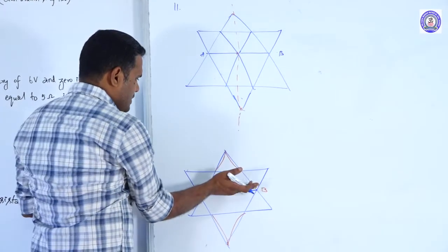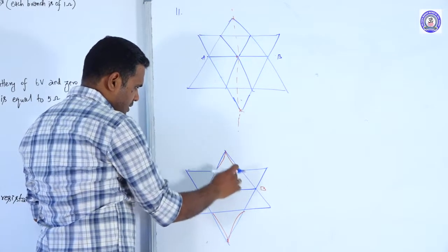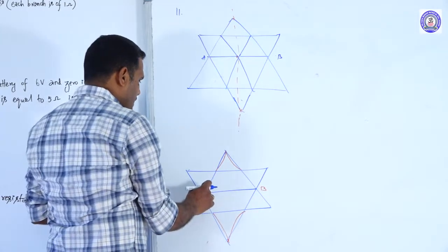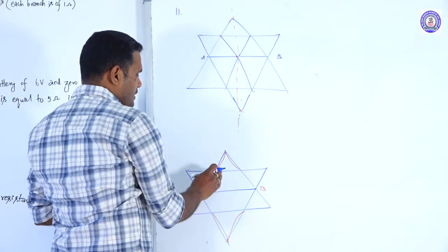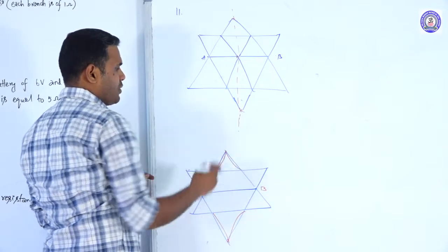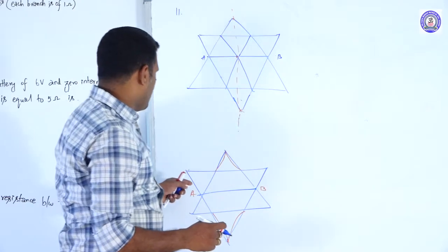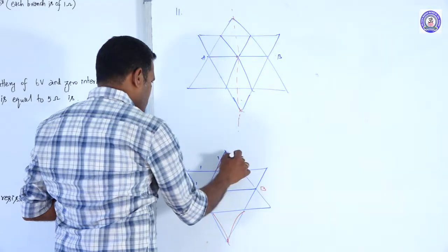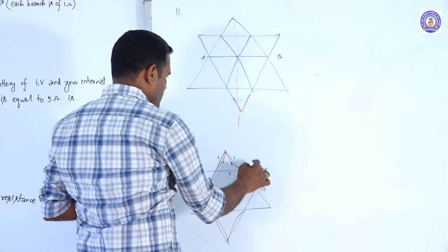Now, there is a symmetry about this reference line AB. This circuit arrangement and this circuit arrangement both are similar, they are symmetrical. So, if I solve the effective resistance for this particular arrangement, then I can apply that for this arrangement also, and then finally I can find out the effective value of resistance across AB. Here, this resistance is 1 ohm, this one is 1 ohm, this is 1, this is 1, this is 1, this one is 1, this one is 1 ohm, this resistance is 1 ohm.